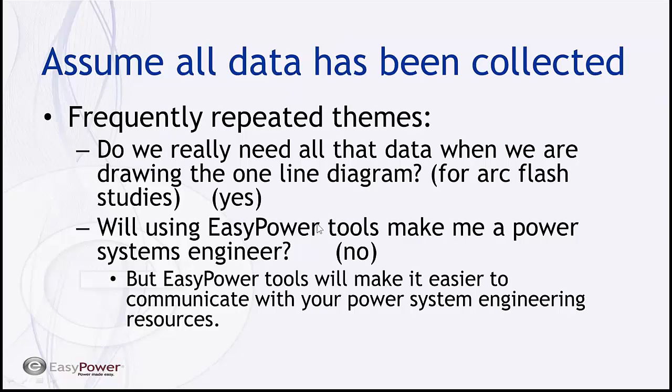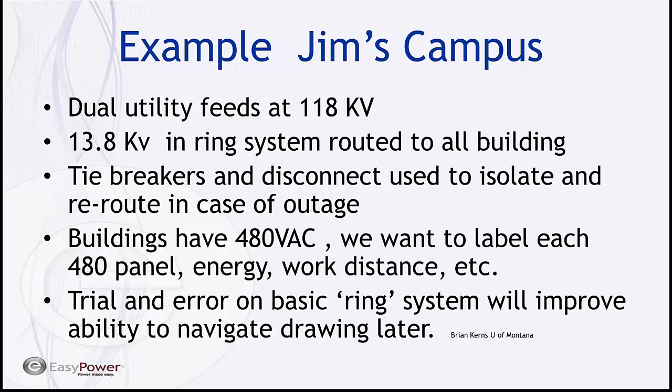We're going to jump into this as we start drawing the one-line diagram, now that the data has been collected. But as I say, you want to play with the tools ahead of time, because very frequently people will come back and say, do we really need all the data that's being asked for? And the answer is yes. By building some trial one-line diagrams, you'll see how vital cable data can be, because it directly impacts the impedance and the arcing time used in calculations. Finally, the tools won't make you a power systems engineer, but they'll make it a heck of a lot easier to communicate by exchanging files and looking at the same data whenever you're talking about your system.